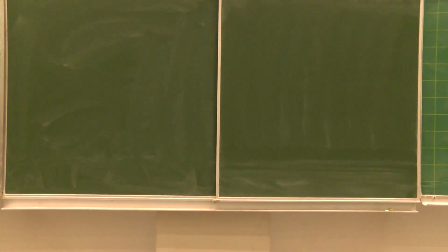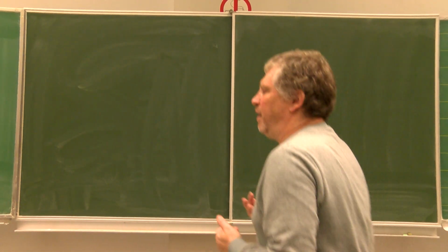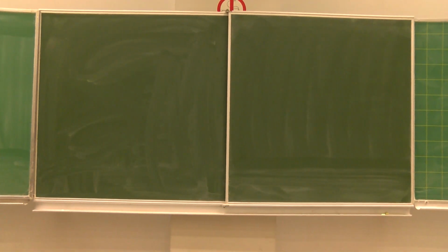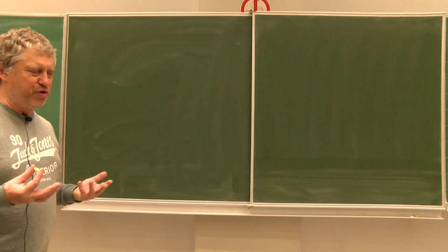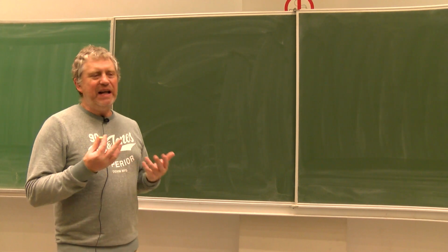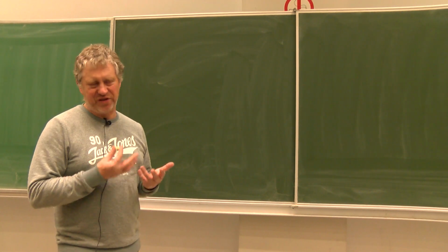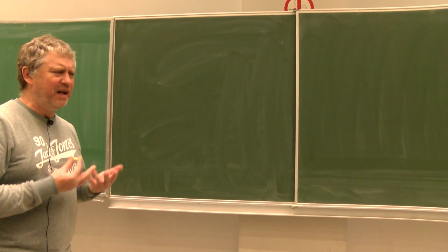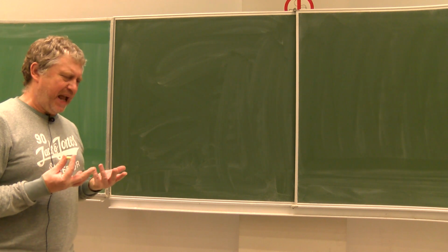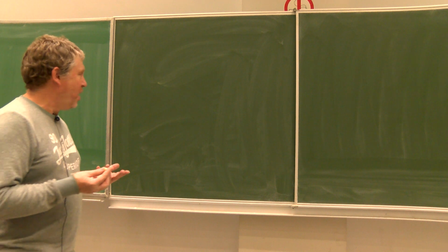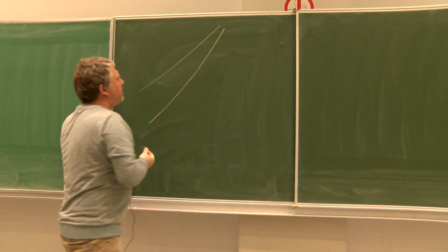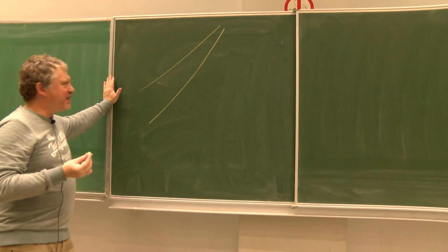But let's say if you avoid all these problems, if you take a lot of margins, technical solutions with variable inlet guide vanes, wide chord blades, if you have leading edges of blade that have been reinforced using laser shot peening, for example, we could ask the question, as we said at the end of the last lesson, why do we need such a distance between the surge line and the steady state line?